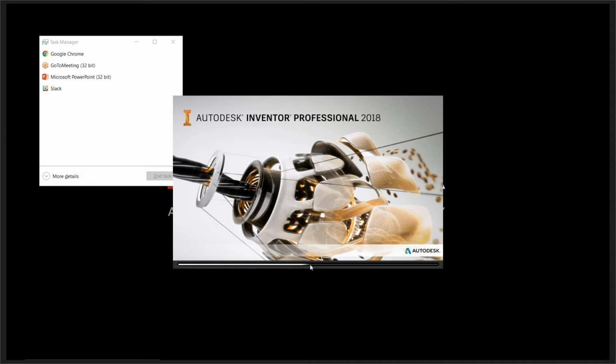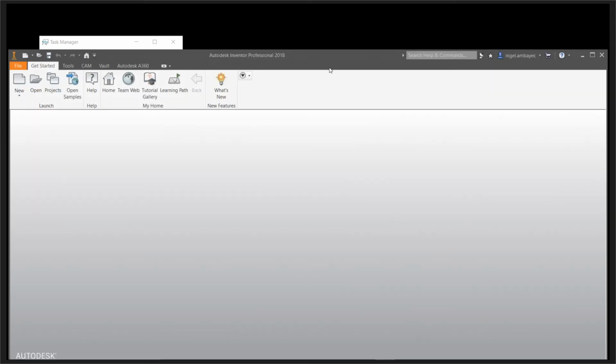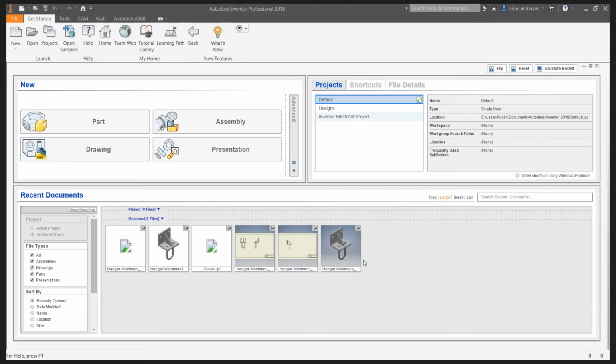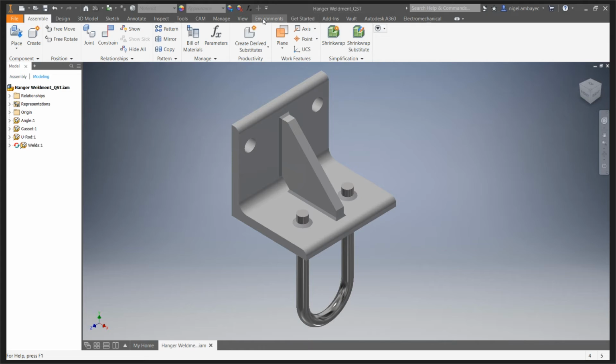Yeah, we just had a dialog box open on another screen. If that happens to you in Inventor, you can open another session, or even better, you can change the screen resolution. So I guess I turn this into a support case. You can change the screen resolution on your computer and change it back, and then everything will jump back over if this happens to you.